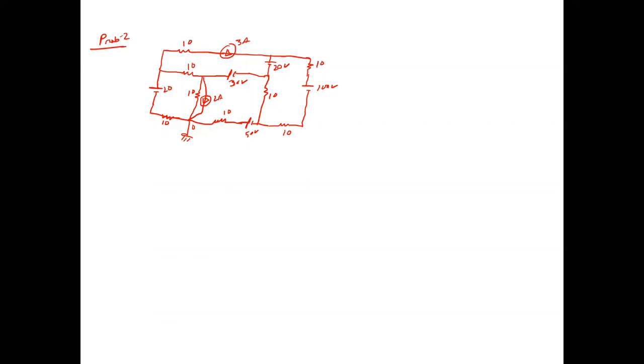Okay, now we start our first point. Suppose all this is clear. So this is the current source, so current source, this resistance. What will happen to this resistance? It will vanish, sir. This resistance vanishes because it is in series with the current source. Okay, yes. This resistance is only a resistance, with no voltage source or current source.